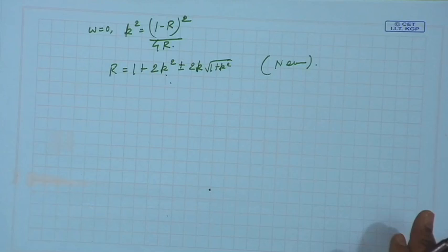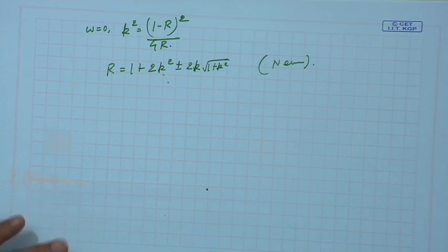So, filters generally are not matched. You have faced the music in image parameter based method. Here also there will be mismatch, but I again refer you to the 9th lecture of basic tools of microwave engineering, where we have learned how to tackle impedance matching problem. So, you can always design with this filter a quarter wave transformer, or you can also add an extra additional filter element.